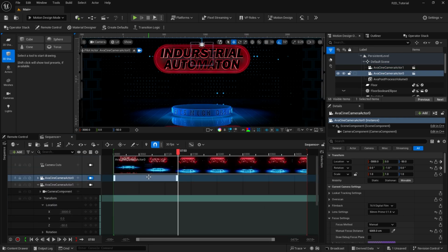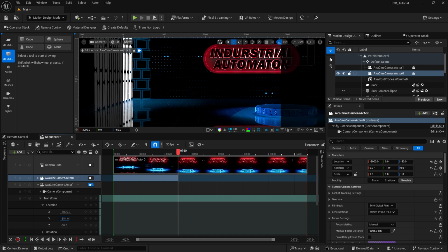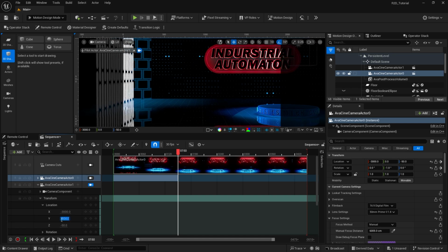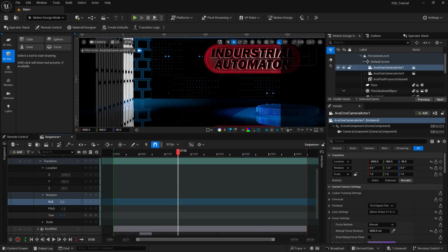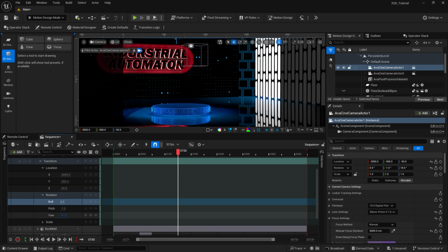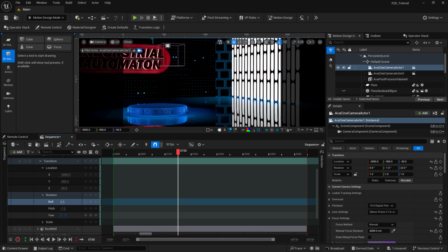To create this second camera move, I'm going to select that camera, click right there. Now we're seeing that camera. And I'll go down here into the transform properties and I'll start sliding this camera over. Bring it over a good bit. I'll try -900 on that and then rotate it. Need to drop down into my rotation properties here and rotate that on the yaw option there. Set that up, maybe about like that. We'll try it and see.